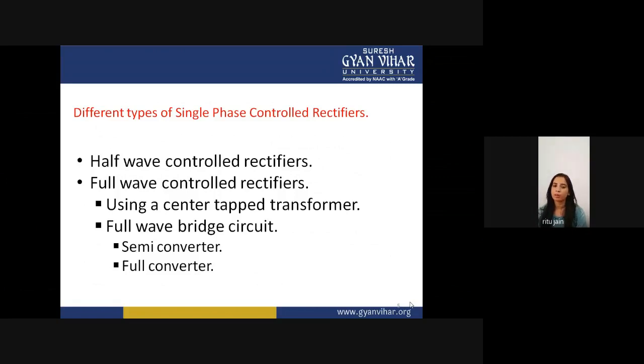In a single phase converter, whether it is a half wave control rectifier or a full wave control rectifier, you are using only one phase and one neutral wire. Okay? And the components we use to make the half wave rectifier and full wave rectifier in single phase are fewer than the components required in the three phase controlled rectifier, right?